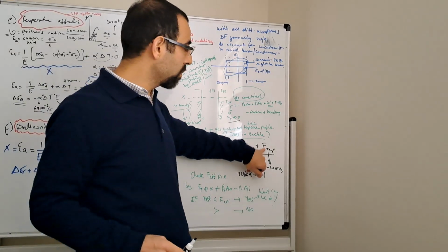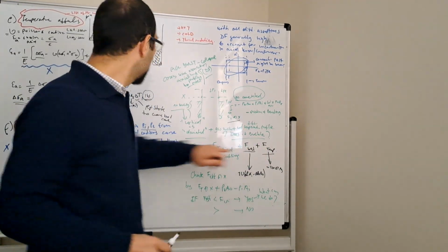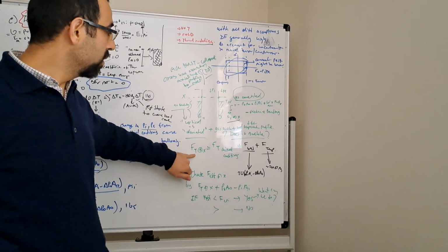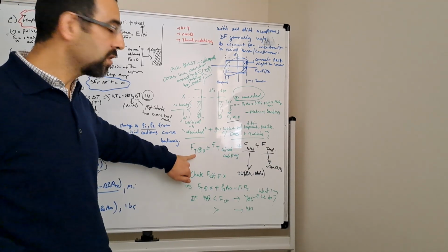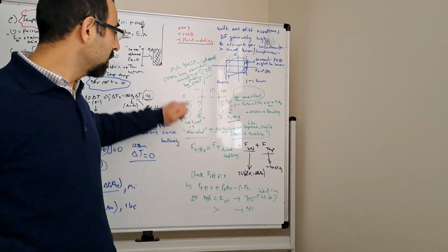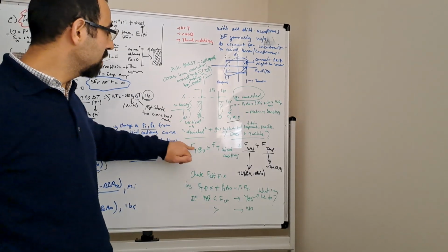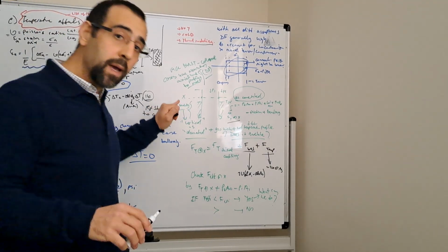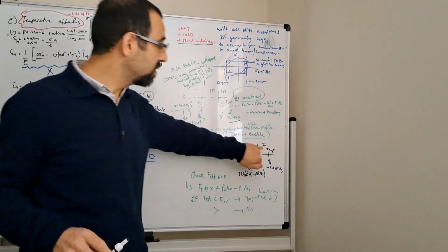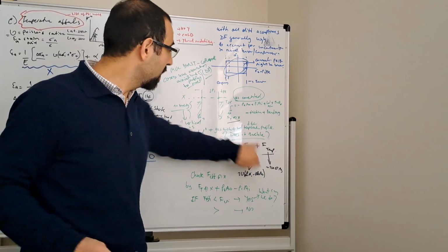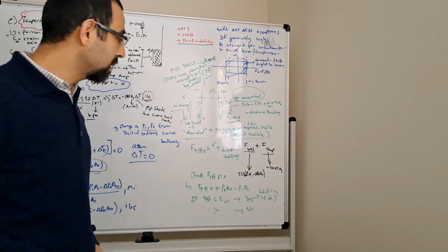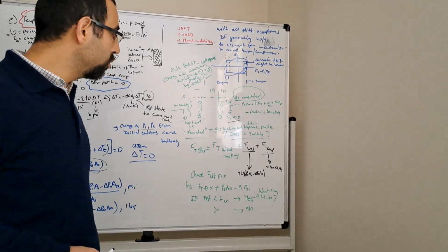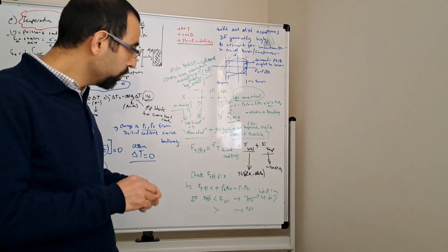So that's why you will have some kind of associated warming up, and then that warming up will cause some additional compression. Then you will come up with a true tension. Let's say we call it X. So at X you still have the initial condition internal pressure and external pressure, the gas kick internal pressure and external pressure, and the initial condition temperature and the gas kick final temperature. So you will basically sum everything up, and that will give you the true tension in this load case.